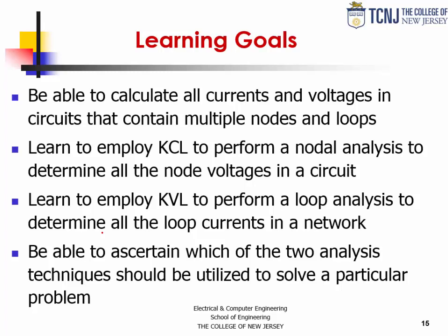Then for the mesh analysis, we gainfully employed Kirchhoff's voltage law to perform loop analysis and write those loop equations in terms of the mesh currents, and solve for the mesh currents using linear system techniques or matrices, and then use Ohm's law to find all the quantities of interest, the real currents through the components as well as the voltage drop across them. And in these examples, you were able to see when it is better to use one technique over the other.